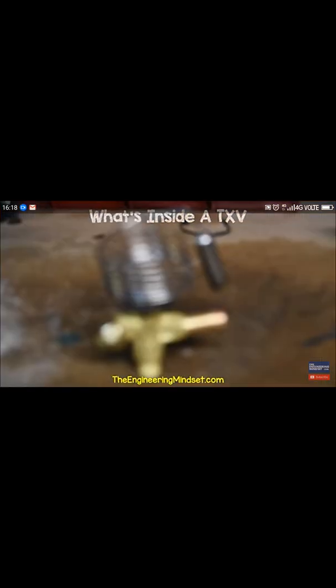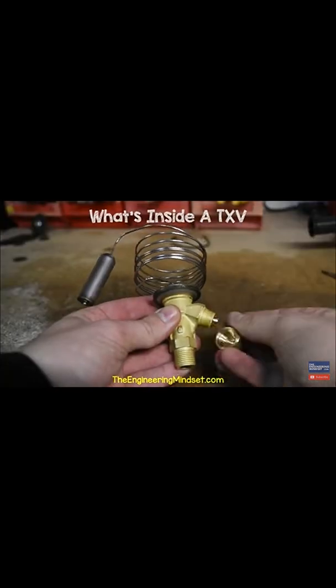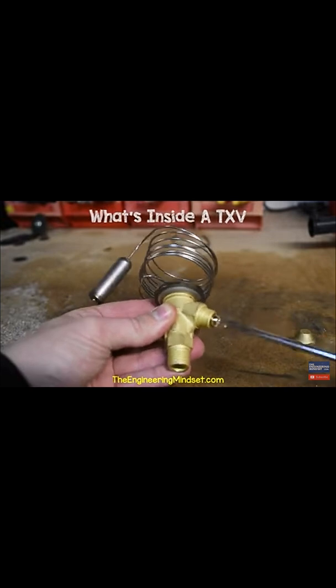In this model, which is a T2 thermal expansion valve, we have the main body, which is made from brass. On the body, we have the refrigerant inlet at the bottom of the valve, then the refrigerant outlet at the side. And on the other side, we have a cap which can be removed. Under that cap is a screw which is used to manually adjust the superheat. We'll see how that works later on in this video.